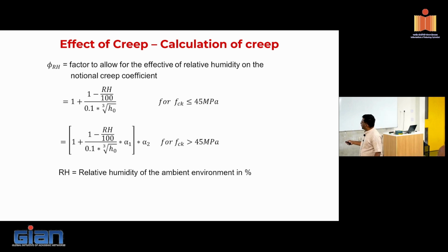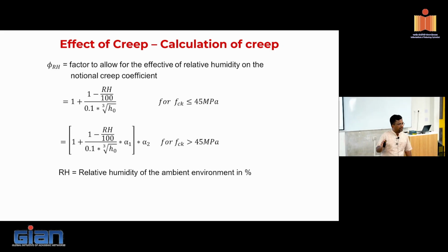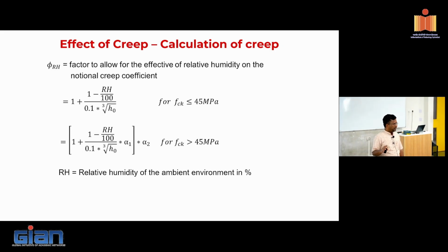In a nutshell, it's very simple. Higher the relative humidity, less will be the creep, right? The more dry the air is, higher will be your creep. Okay, so that's how it's being incorporated. In addition to that, there is an H0 factor. What is that H0 factor? That's what I told you.